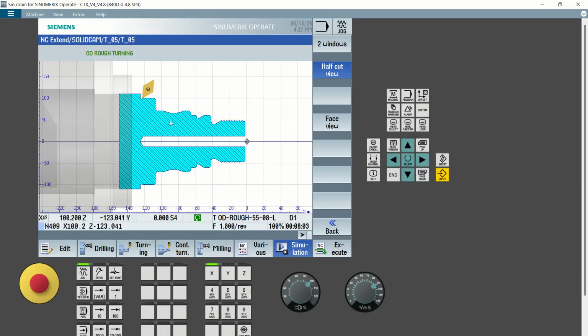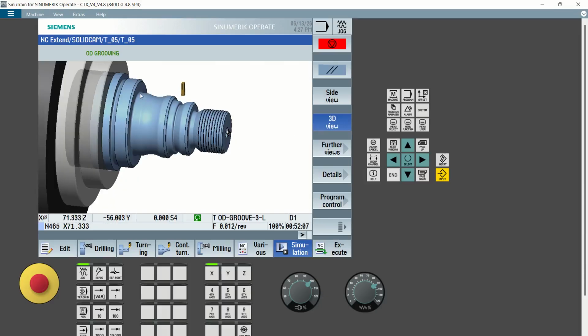There are various factors you need to consider when you're programming, not just programming. And this is only for teaching purposes. But when you're doing actual machining, you need to understand the overhang distance. For overhang distance, you take the maximum diameter of the final part, times 1.414, to know the distance of overhang, so that it doesn't wobble and the tool won't affect the uniformity. And this is what you require when you come to a center.